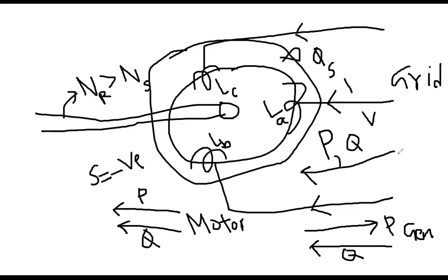Now see the consequence. Everybody say, what is the consequence of providing reactive power to a coil? For example, we have a coil, just think about any set, and we are injecting reactive power. What will be the consequence of sending the reactive power to a system? Like what we learned in the first chapter, three-phase circuit, if you send much more reactive power, then the power factor will be low. Because these are coils, once you send the reactive power, the power factor naturally gets low, a low lagging power factor.